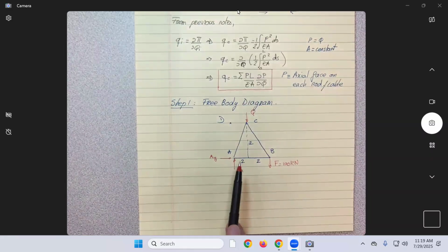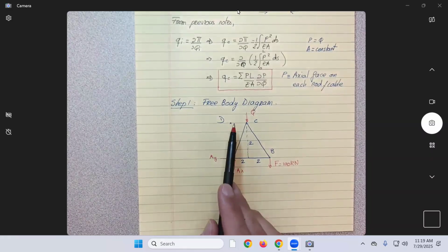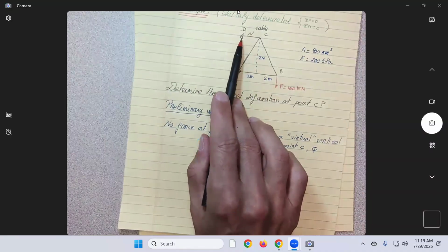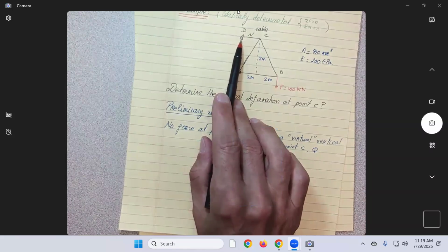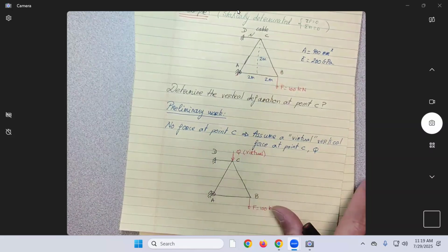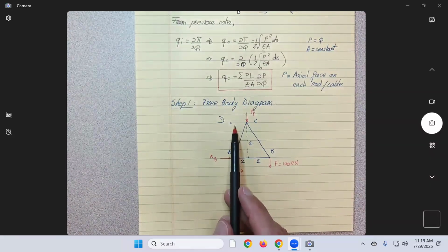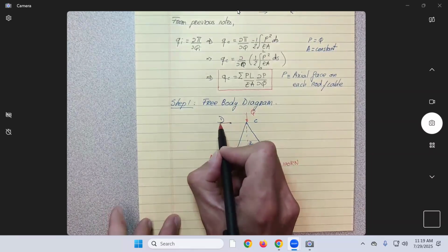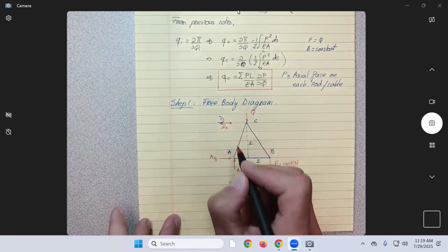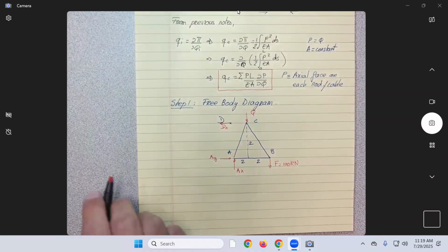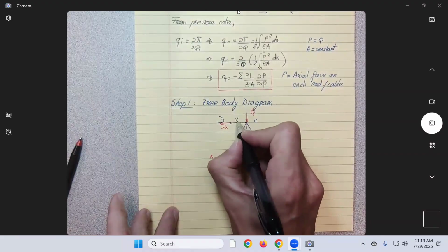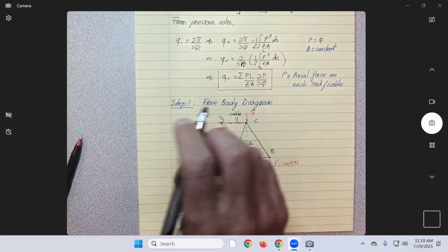So in this problem, we have unknowns AX, AY. What would happen if we had another simply supported point here? This would give 2 reactions, Dx, Dy, so the problem would become statically indeterminate, which is not a good sign. So why do we say this is a cable? Because then we only have one reaction, and we know it needs to be in tension, so I'm going to draw Dx in tension on the cable.